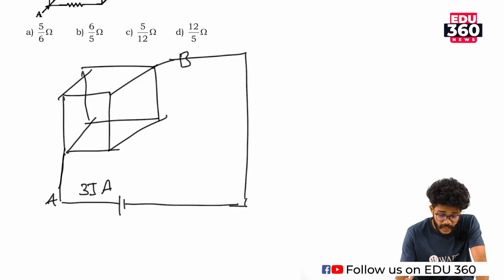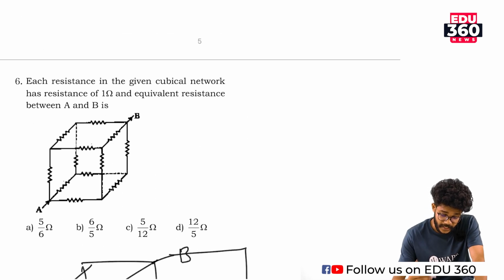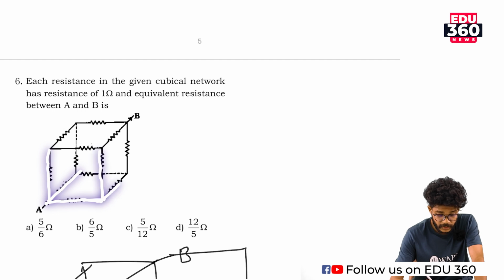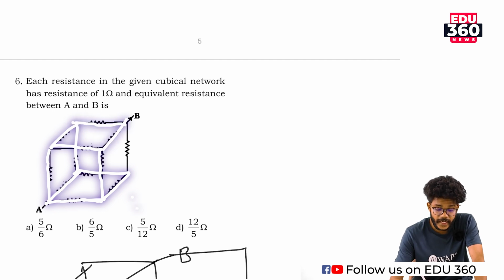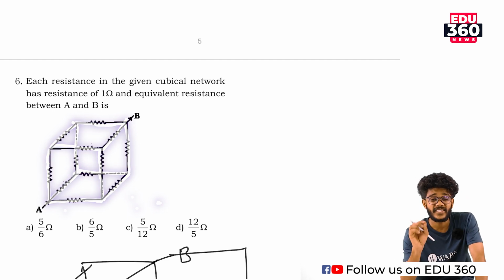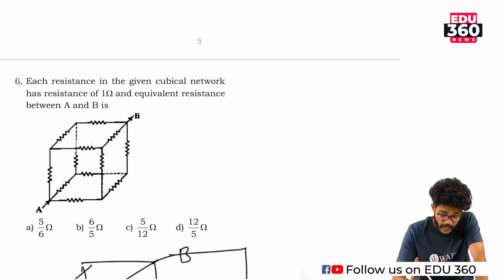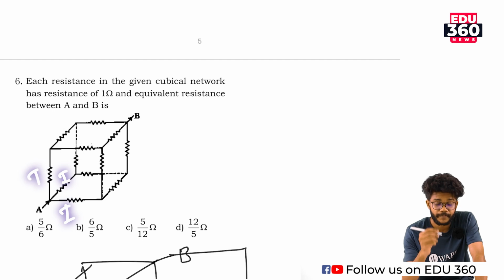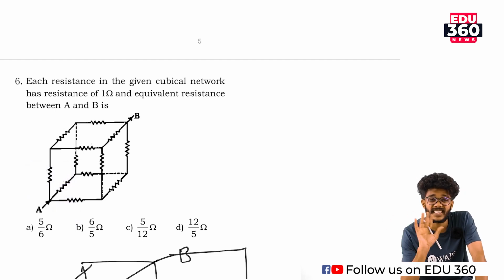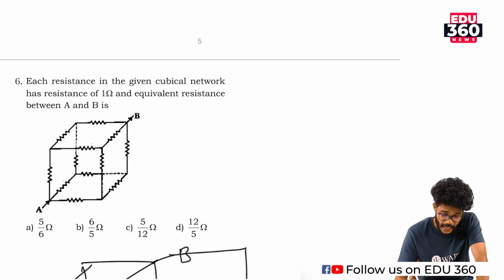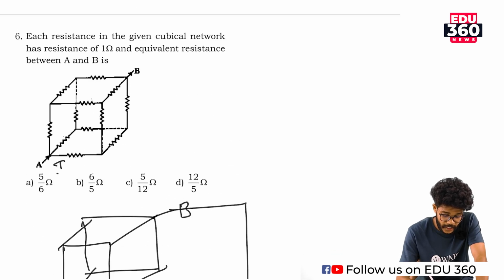Okay, see, actually the circuit is identical, in the sense that it is divided into 2 parts, and each part is connected to another 2 divisions, and each is coming back. So we can say that each branch divides the current equally. So I through here, I through here, I through here, because all branches are equally connected. Each resistor has 1 ohm of resistance, so each branch has equal current drop. So I am writing I through here, I through here and I through here.